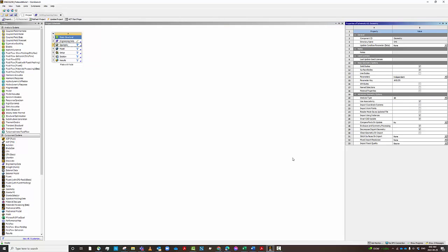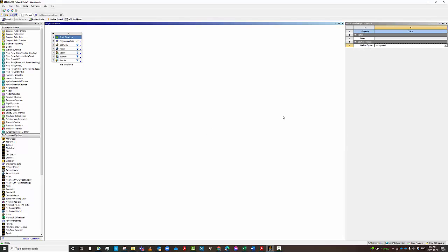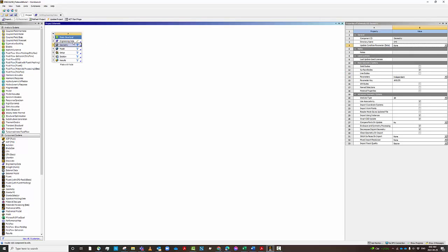Because we are solving the blade problem, which is a standard problem. It's a plane stress problem, okay? And you can always, if you want, get rid of the solid body because we are creating surfaces. So if this messes up, you can always click here and go to properties, and it will show. If it has disappeared, you can always bring it back from here. So that's 2D, and I have selected surface bodies here. You can see line bodies if you're solving 1D, or solid bodies, right? So I'm going to keep it that way.